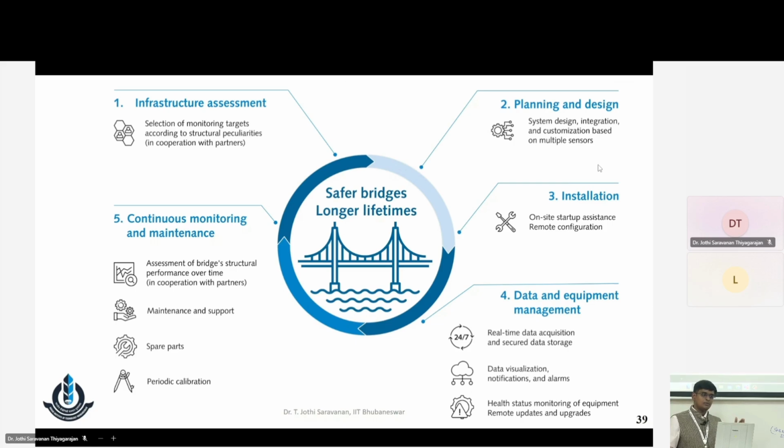At the end, there is continuous monitoring and maintenance, which is real time and also for long-term monitoring. That is very important. It's not that I just go, monitor and come back. I have to install and monitor for the next 3 months, 6 months. This monitoring will help you understand how your structures behave under various loading conditions, which is a very important point we have to take care of.